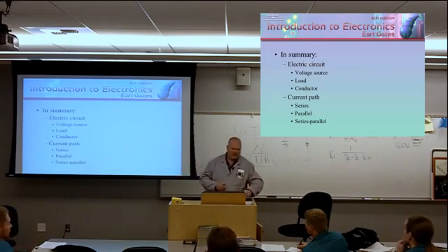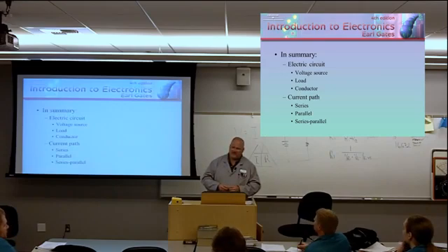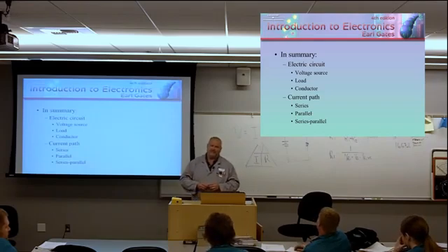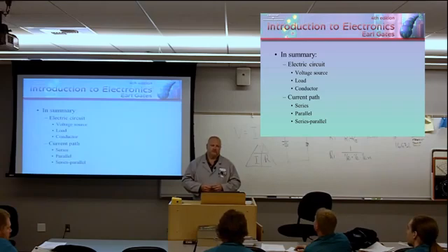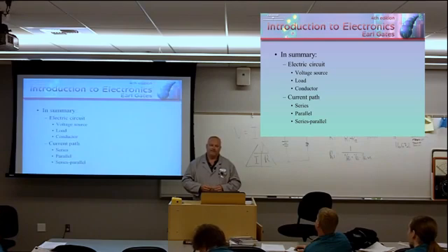I don't know, in mobile audio, did you encounter any of that stuff, where disconnecting it for a period of time would fix the problem? Yeah, if you did a hard reset, touch positive and negative together, make sure the circuit's completely unenergized. Airbag lights, some control systems would do that. To make sure that everything dissipates inside.